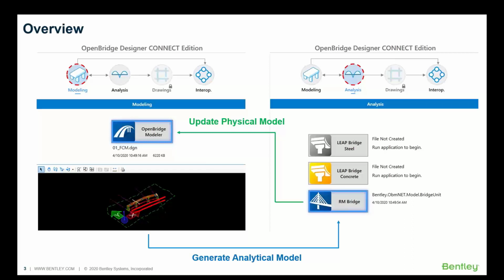OpenBridge Designer enables you to perform bridge design using two workflows. When the BIM workflow is selected, the engineer can proceed with design by the BIM process. Standalone allows you to ignore the BIM workflow and design the bridge using each of the features in OpenBridge Designer. Also, you can generate the analytical model from the physical model automatically.